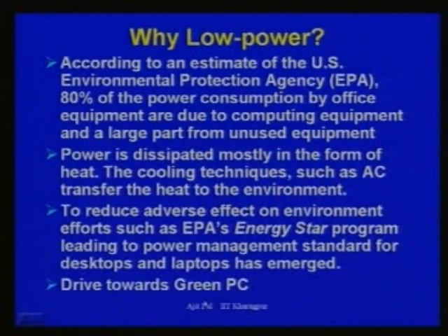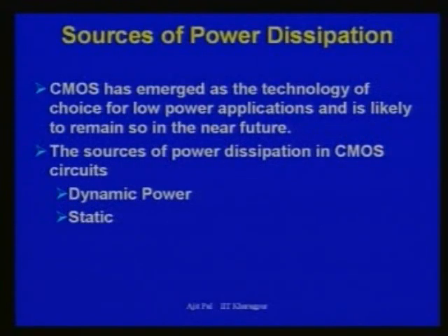This is because of this drive towards green PC and the standards which have been developed for this purpose. So you see, low power methodology has already been adopted in the case of your laptops and other equipment. Even if you don't use some battery operated equipment for some time, it will automatically switch off the power hungry subsystems. So now I believe you are convinced that low power design is very important. Are you convinced? Okay. So now let us look at our enemy, the sources of power dissipation.